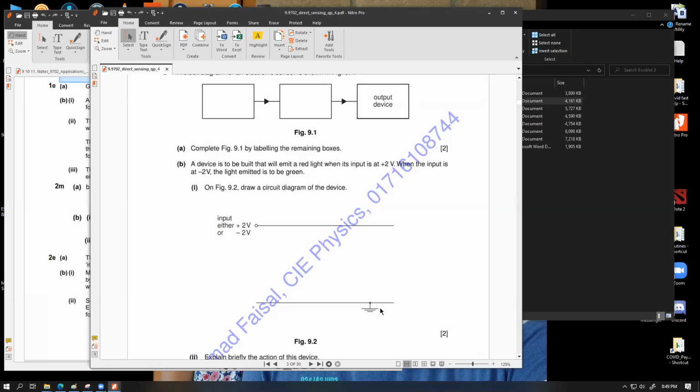That's the theoretical definition, but for practical purposes, the way we decide that an earth connection can be a large enough metallic body that have so many free electrons that that big number can be considered to be infinite for our requirement. For example, for a car's electrical circuit, the entire metal chassis is considered to be the earth.